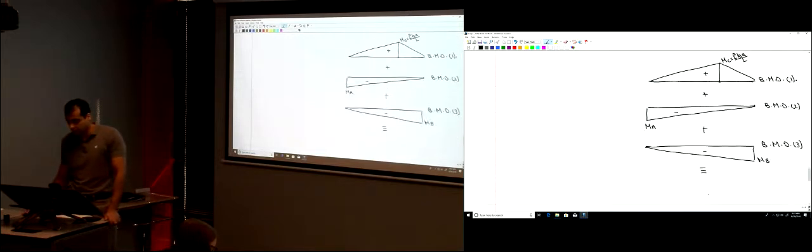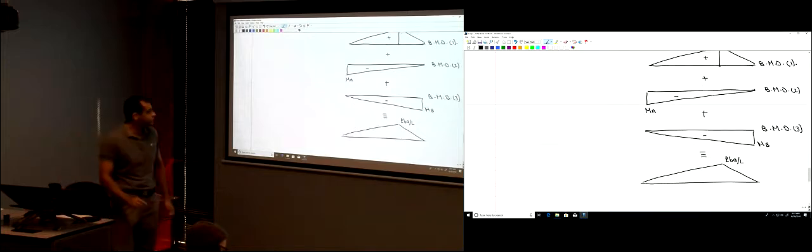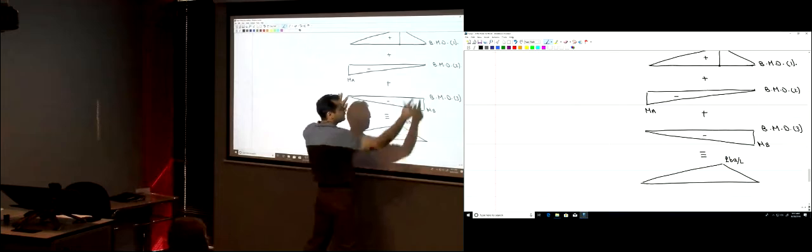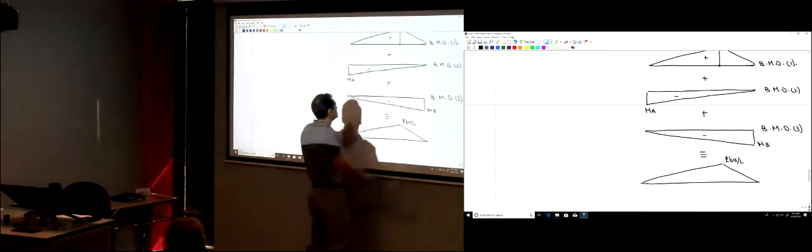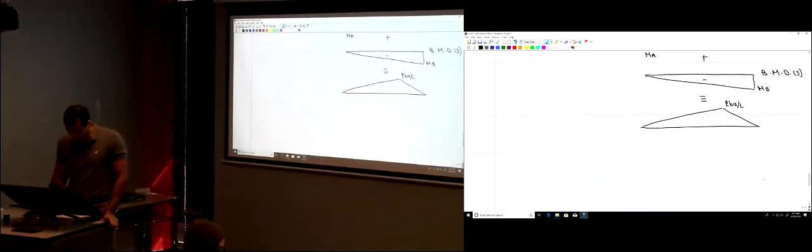Okay? So the positive moment here, we had something that looks like this. PBA divided by L, and then for the negative moments, here we're going to have MA plus 0, and here we're going to have MB plus 0. So it's MA on one side and MB on the other side.